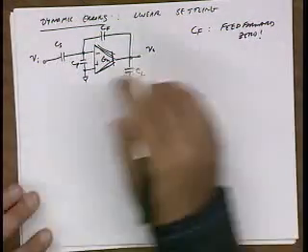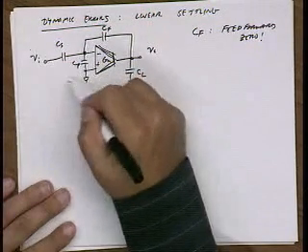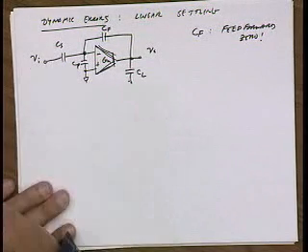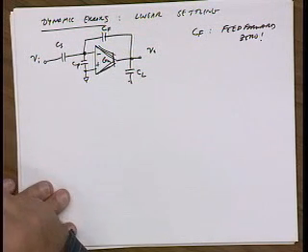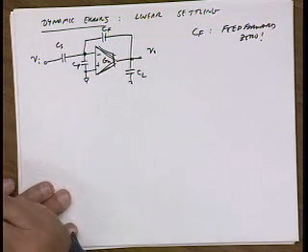What else? In the input node, we have a mirror effect on the CF. Yeah, but at the input node, that just adds to these capacitors. Does it really hurt us? Let's say I voltage drive this. Any other poles or zeros in the circuit?